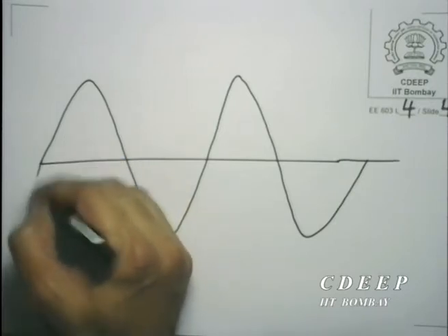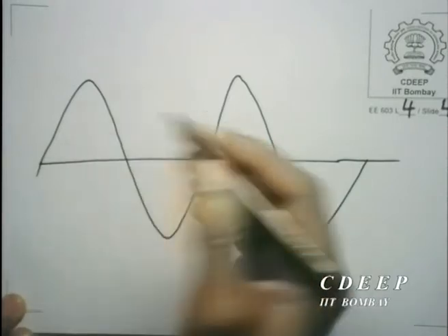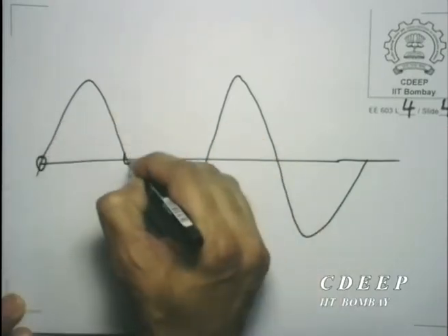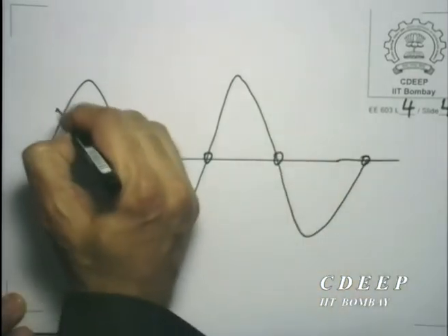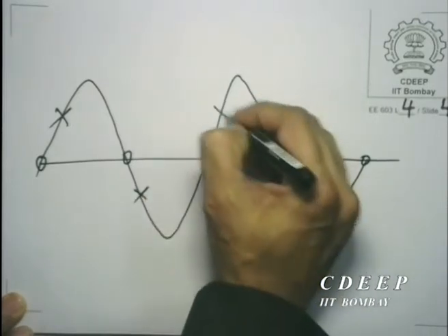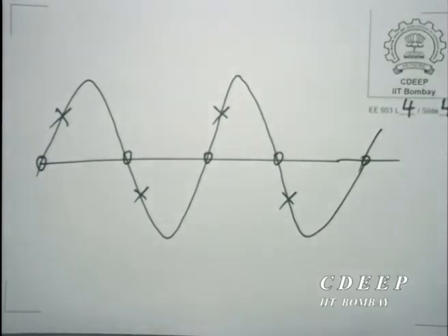Now, the original spectral component, sinusoidal component and the mirror image would cancel one another if you sampled here. It would give you all 0 samples. On the other hand, if you were to sample here, they would not cancel one another. So, it is not obvious that they would cancel one another, it would depend on the point of sampling. But there is a potential problem of their cancelling one another if you happen to begin the sampling from a 0 crossing. Okay. All right.